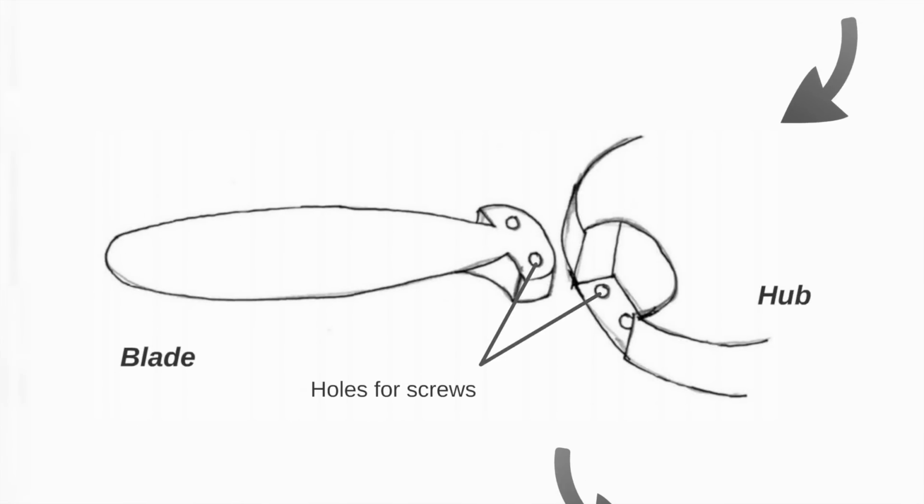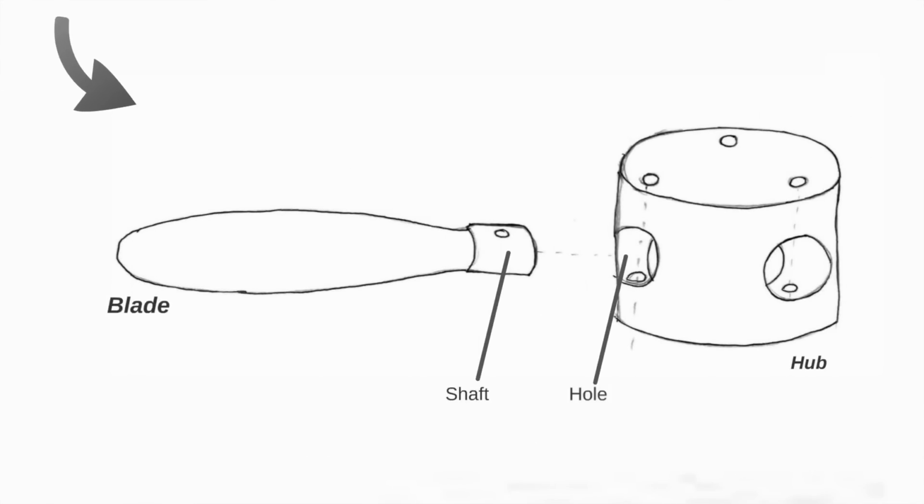Following that, the use of screws was introduced as a solution to counter the centrifugal forces from the blade rotation that might shear the blade out from the hub. Sufficient area for drilling was a secondary consideration. Employing a shaft and hole in a circular blade joint addresses the problem with blade rotation, and a screw holds the blade against the centrifugal forces and also fixes the angle of attack of the blade.